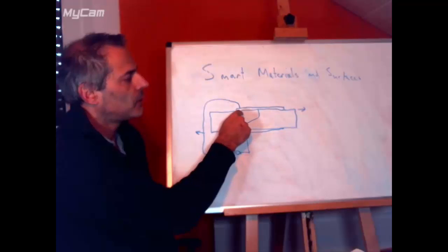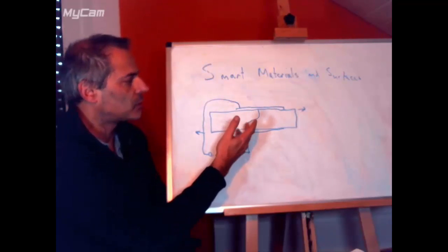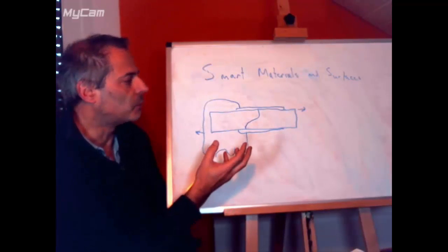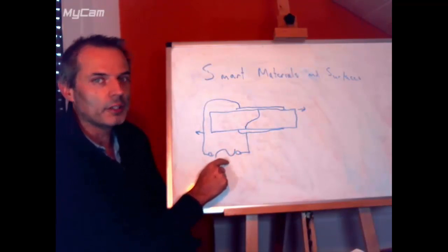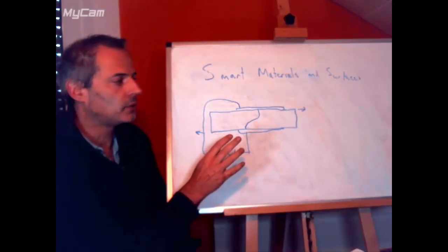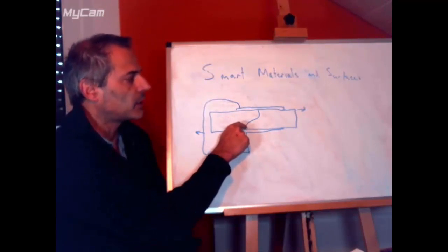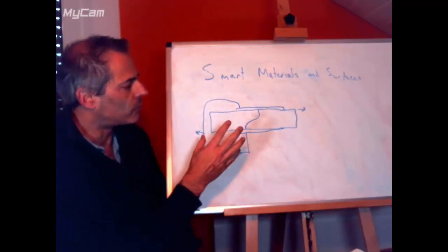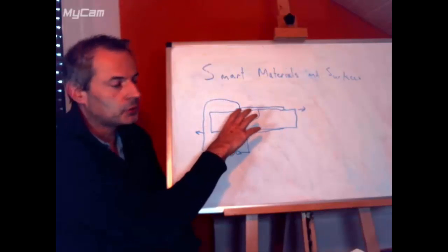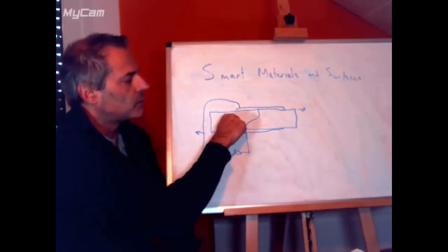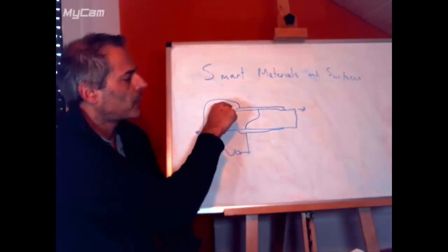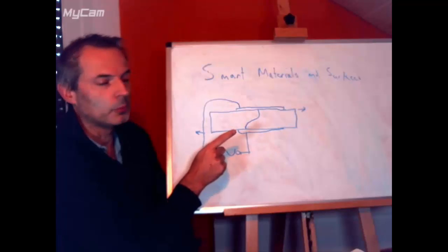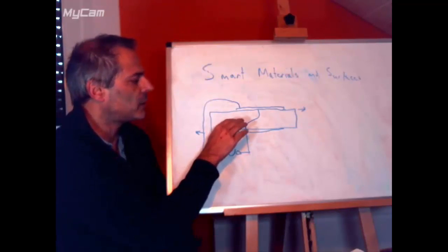When it shifts, nothing interesting happens, or something very interesting happens. It moves, but it's not oscillating. We can't measure anything. If we vary the frequency, we can find resonant frequencies where exactly one wave, or in this case half a wave of the acoustic wave, fits into the thickness of the crystal. I've not considered the thickness of the metal, but that will also be affected in here.